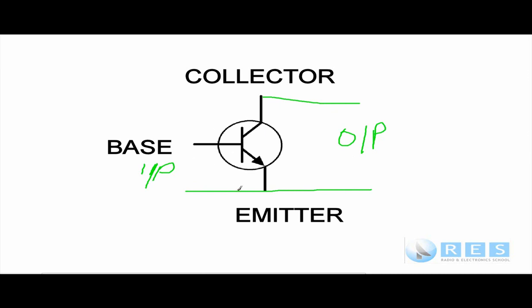A transistor amplifies by changing the base emitter current. If we change the base emitter current, we change the emitter collector current by a much greater amount. If it's a silicon transistor, we need at least 0.6 of a volt across the base and emitter to make it work. If it's germanium, 0.2.